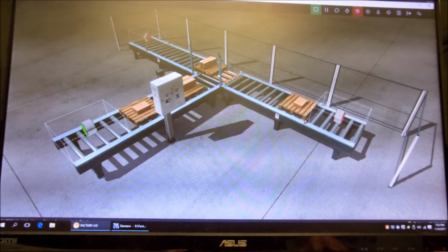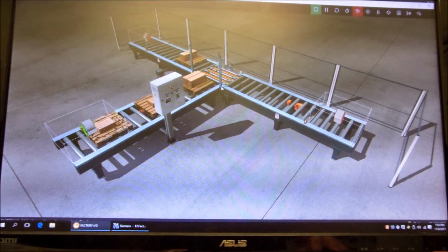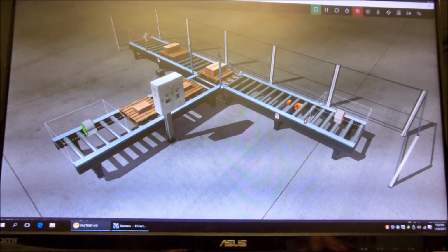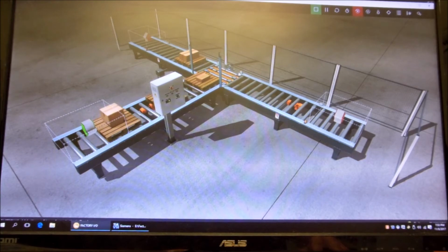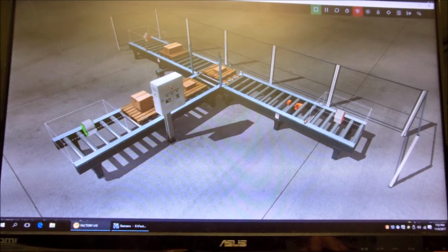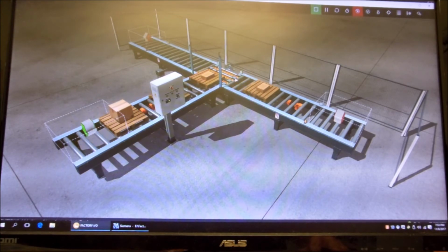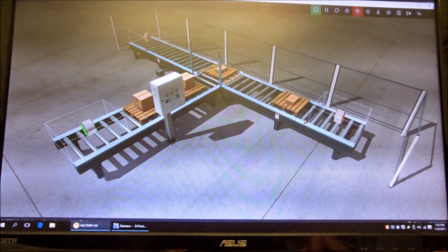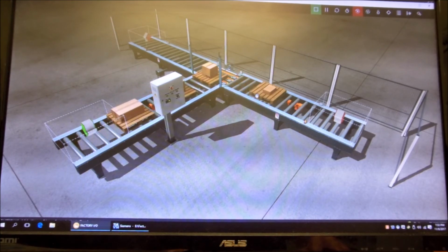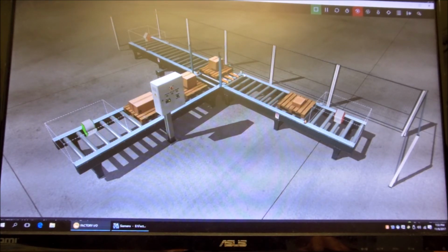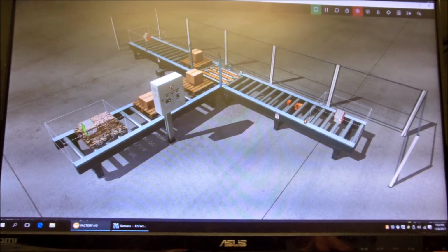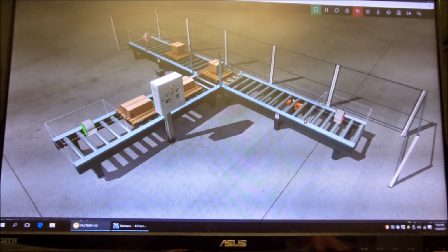And right now we have some through beam sensors, and there's a retroreflective sensor you can see right here to tell you when the box is transitioned from the diverter onto the output conveyor. And when it makes that transition through that retro reflector is when it turns this conveyor on. And then when it passes through the remover thing is when it turns this conveyor off.